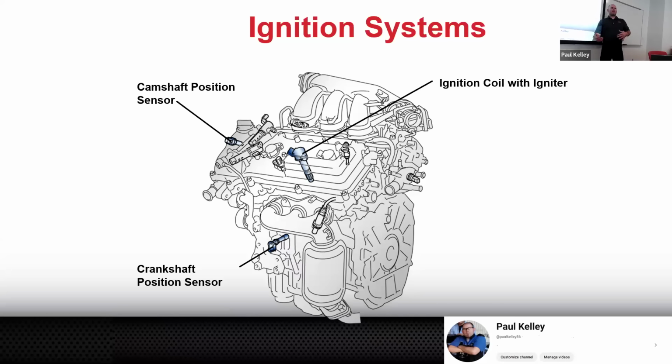If you want to make it a better repair by going on Amazon and buying the Chinese coils that are $200 for all 6 of them, I don't know. Personally, I probably would have done one good brand replacement and not done the other 5, right? So let's say these coils are made by Denso. I would replace a Denso coil with a Denso coil. The Denso coil lasts however many years the car is. The car didn't come with made in China Amazon coils. They didn't come with the flea bay coils. And there's a reason that the original manufacturer is not using the cheapest of the cheapest coils: they're probably not going to last as long.